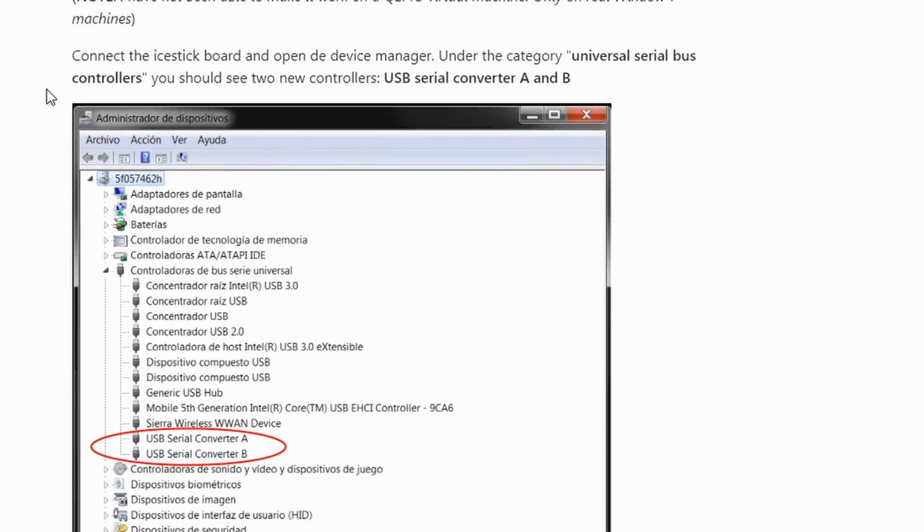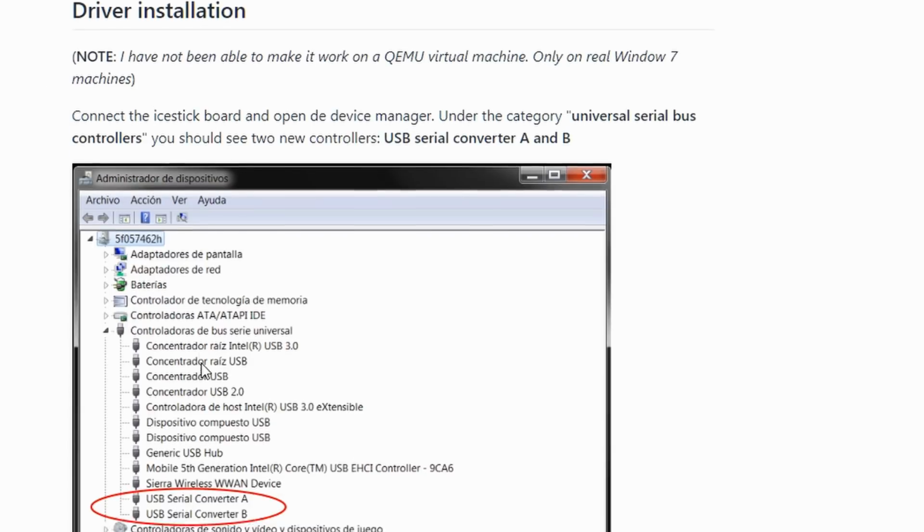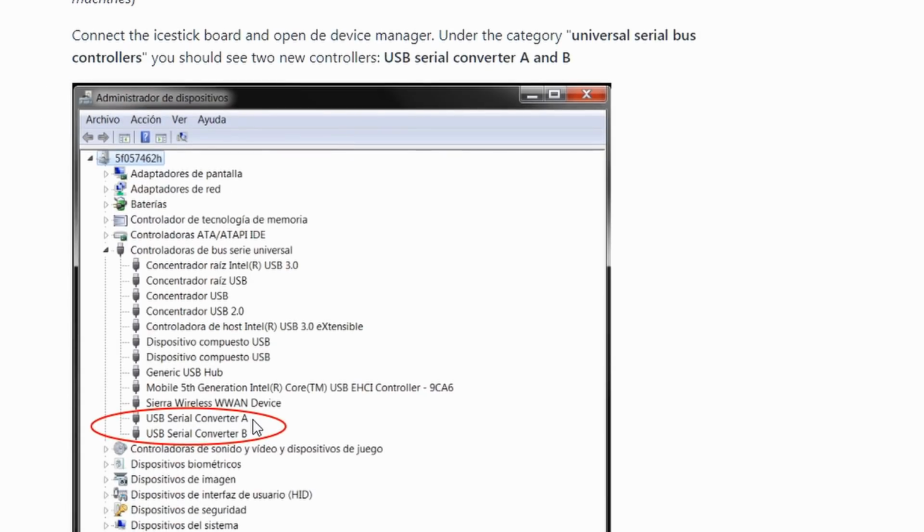The driver that you want to install is called libusbk. So first we want to make sure that we can actually see the device. So I'm going to plug it in again. Now for Linux, I think this is as easy as going into the USB or the device configurations and setting it up properly.